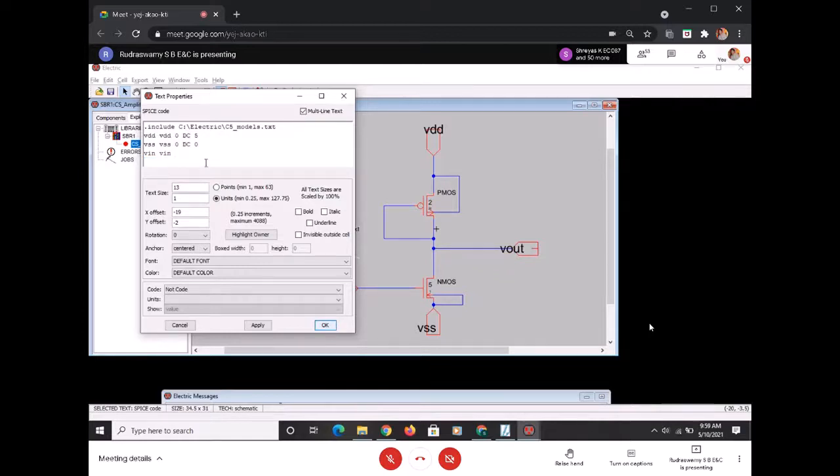Okay, so V in is V in reference 0. It is the sine we are giving. It is not the pulse now. It is the sine wave, because of the small signal model, right? So input is the sine I am giving, not the pulse. Now a very interesting aspect: the first field in this particular V in. I'm giving something like 0.8.